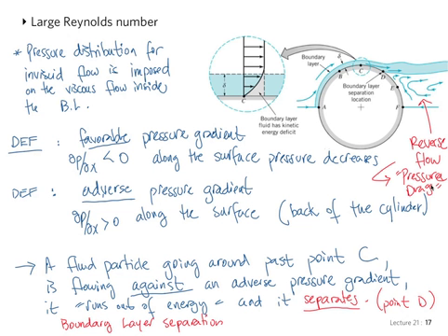The friction makes sort of like there's some added effect of viscosity there fighting with inertia. The particle in the end runs out of inertia, is not able to go all the way around to point F. It separates, produces reverse flow in the wake. Reverse flow produces pressure drag. This is always the case regardless of how small the viscosity might be.